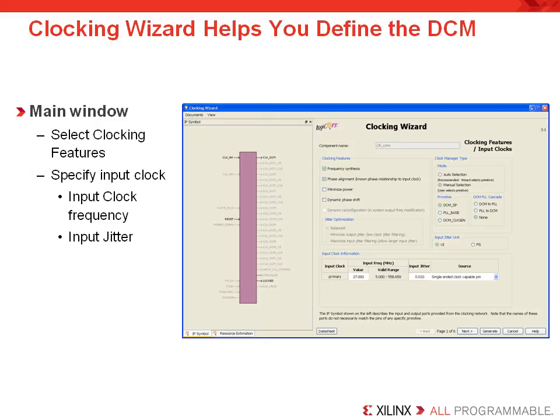The first thing you're going to do is select the inputs of the MMCM or DCM component you want. Select the primary input clock field in the first page. 1 input clock is the default behavior, but 2 input clocks can be chosen by selecting a secondary clock source. Only the timing parameters of the input clocks in their specified units are required. The wizard uses these parameters as needed to configure the output clocks that are desired.